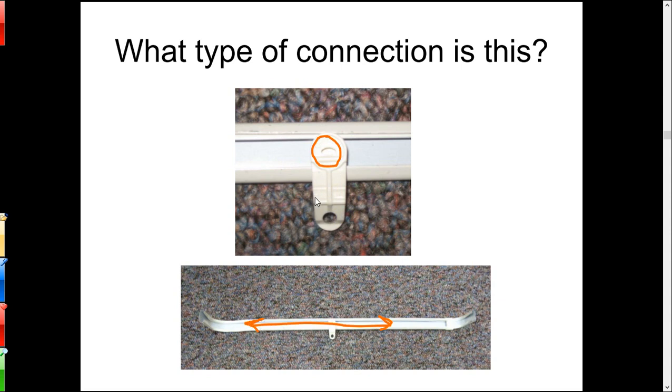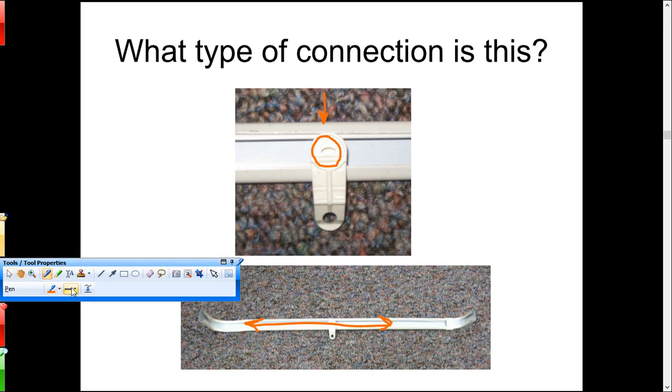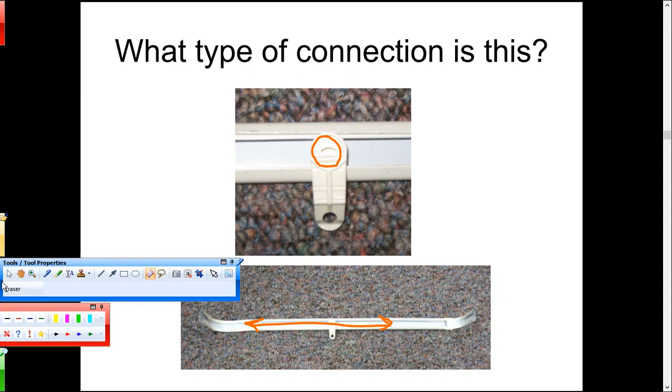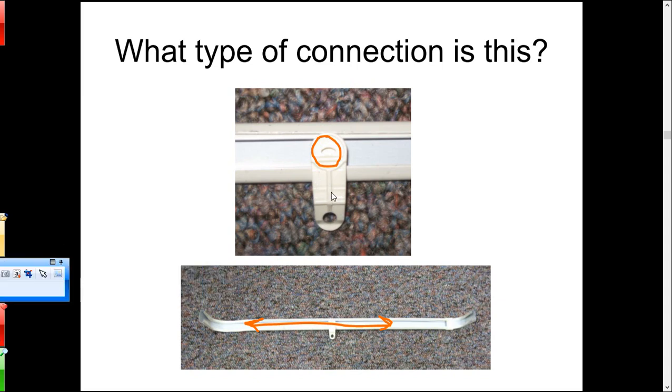Now they're constrained from moving up and down. The force is perpendicular to the surface because they can't move perpendicular to the surface. So they're rollers. You could represent the force of the surface on this roller something like that, or vice versa. Actually, gravity's acting down there, isn't it, in this case? So the force would be up, not down. But regardless, the force will be perpendicular to what you define as the surface. Okay, like so.